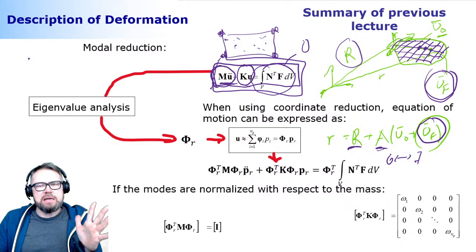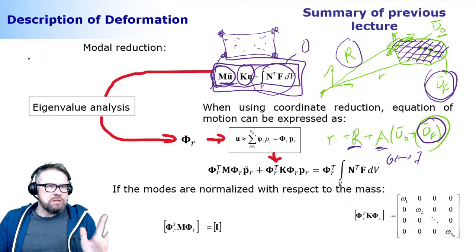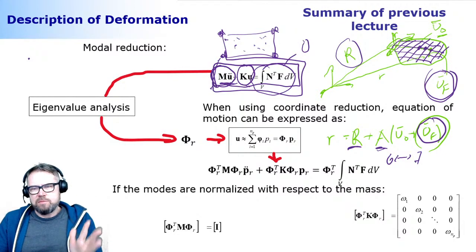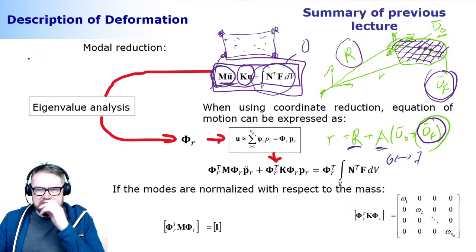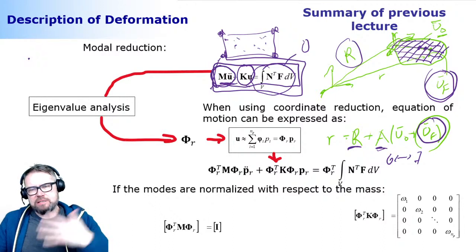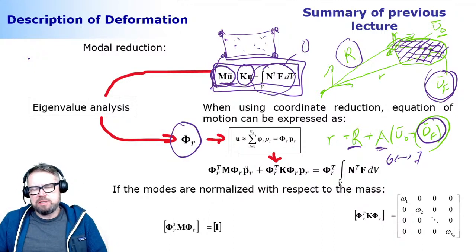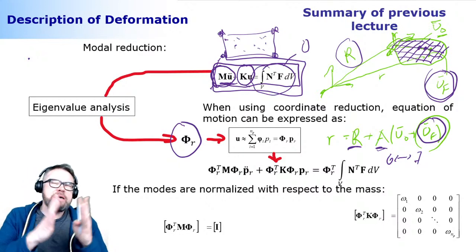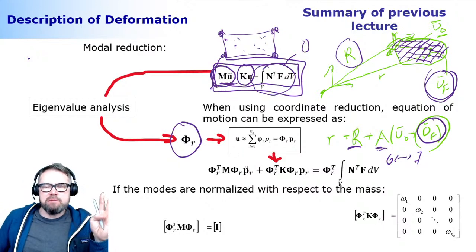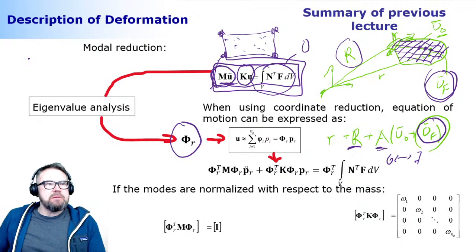Resonant frequencies are in turn associated with certain resonant deformation modes. Now, moving on in this line, we have the matrix that tells the relative ways the nodal degrees of freedom can move. That can then be multiplied by modal coordinates.